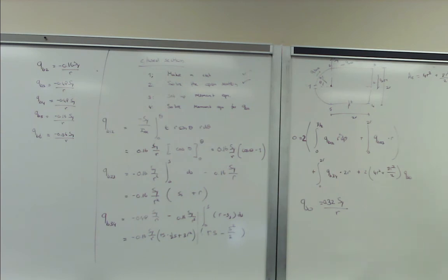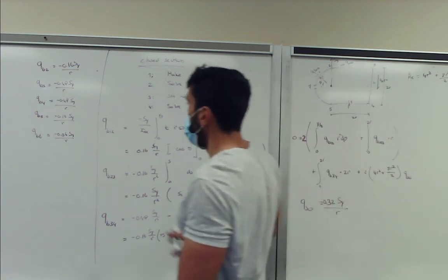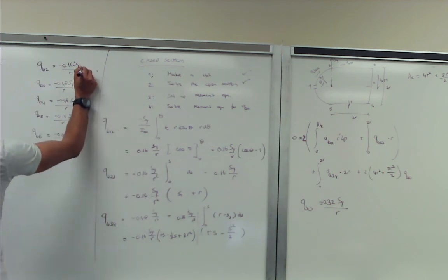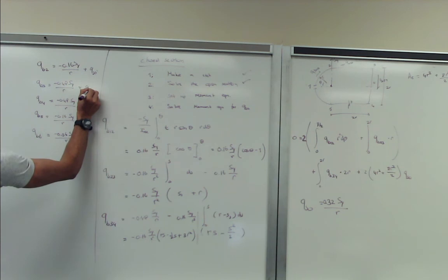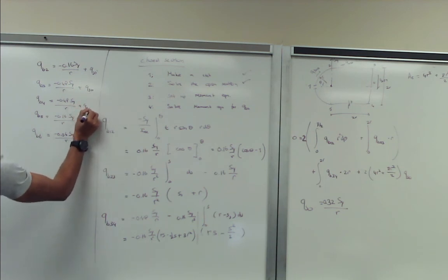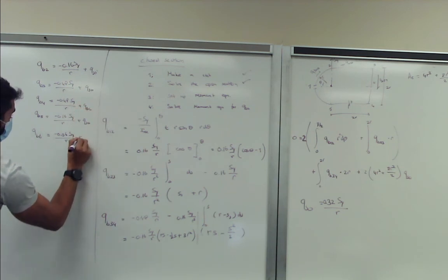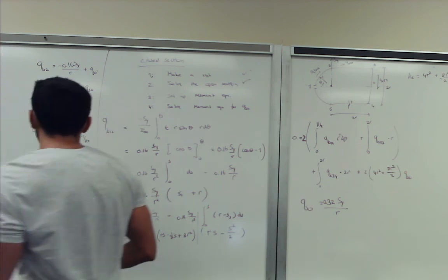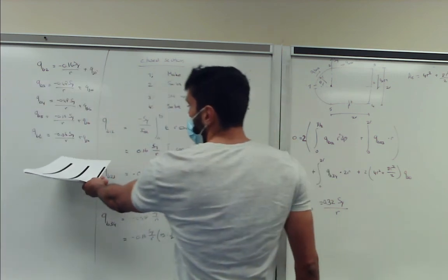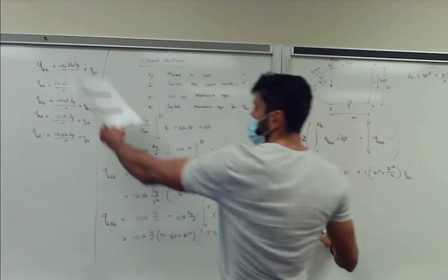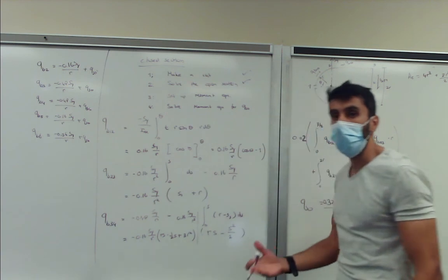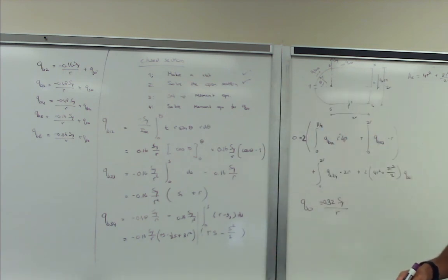And now your final answer would be adding this to all of these segments. So you would have to add QS0 here. So plus, let's just call it QS0, it's easier. This would be your final solution, because this was all the open sections. We have a constant correction shear flow, and we add this to our shear flow locations to get the final answer to it.